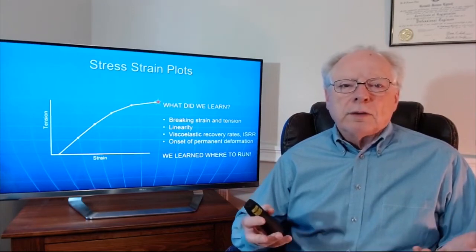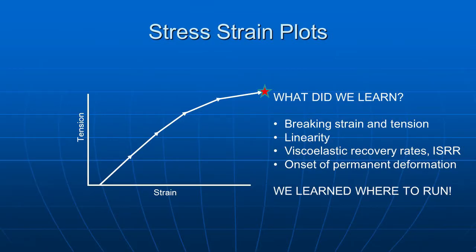So what did you learn from this? You learned about the breaking strain and the web's tension behavior. You learned if the web is linear elastic or nonlinear, non-elastic, and if you can use simple linear elastic math. You learned about its viscoelastic behavior and how fast the web recovers from strain. You learned about permanent deformation as a function of strain.